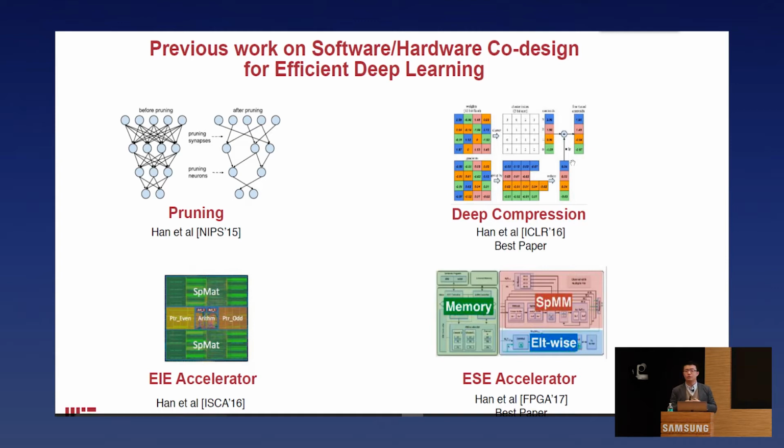Okay? So this means we can have less requirement to fetch the data from the memory, to save the memory bandwidth. However, general purpose hardware is not efficient at supporting compressed and sparse neural nets. So I built the efficient inference engine, which directly walks the sparse matrix and ignores those zeros so that we can save cycles and save memory for inference.